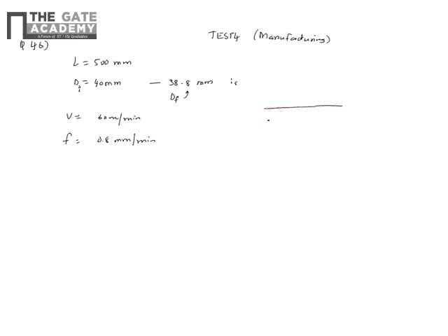So you have the cylinder mounted here and this can rotate as it's fixed on a spindle. The cutting tool is something like this, where you provide the feed to the cutting tool. Okay, and you keep the object on the spindle which has the speed n. So the cutting speed V is nothing but R omega. It's the speed of any point on the cylinder, and the cylinder is in fixed axis rotation about the spindle axis.